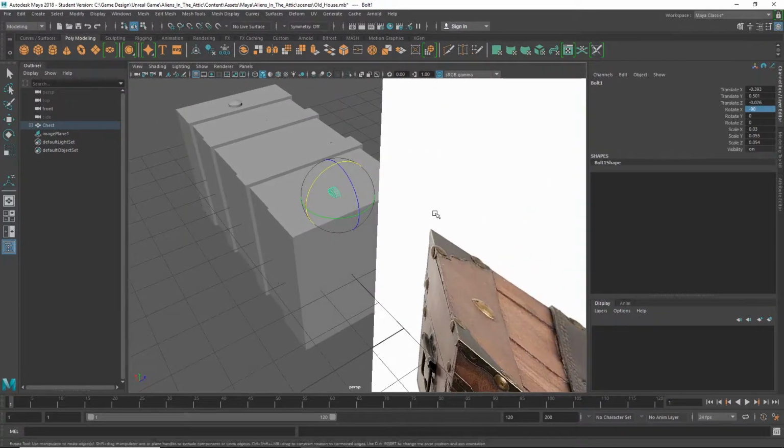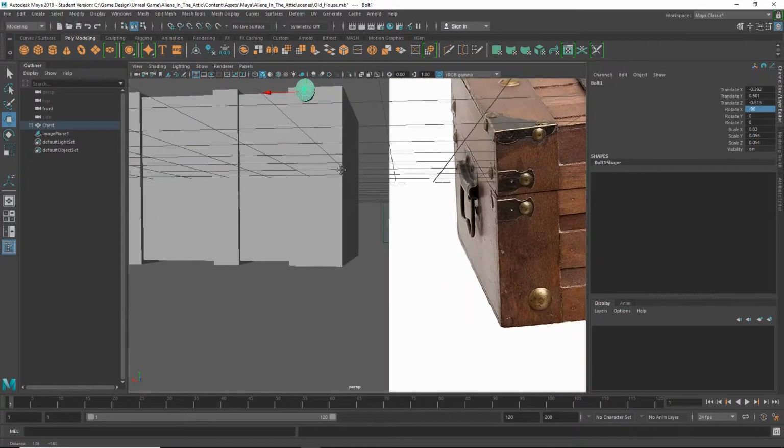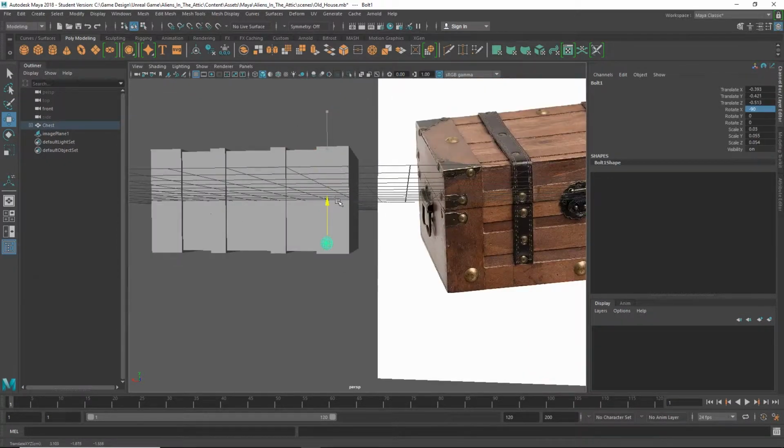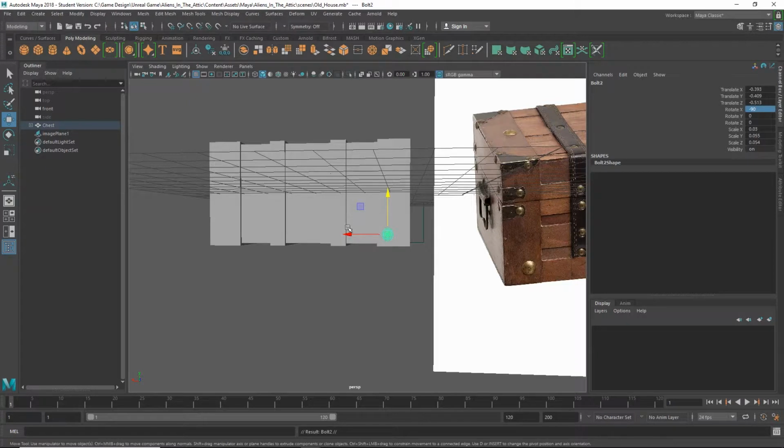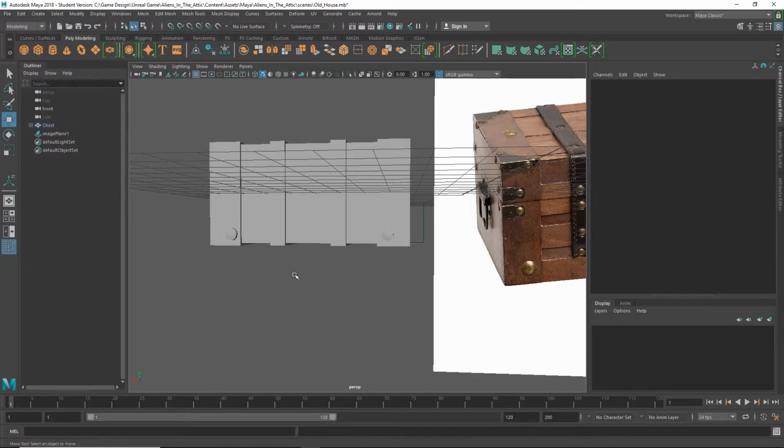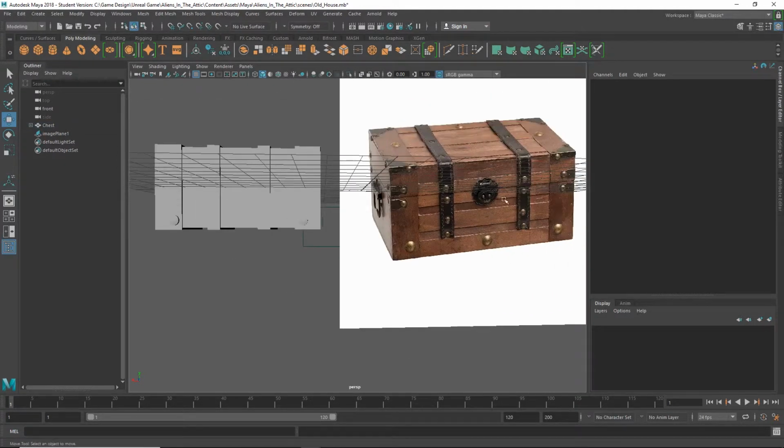Seems like a lot to learn, but when you master all these little things I'm showing you, you'll feel really confident as a modeler, and you'll just buzz through this really quickly. Once again, Control D to duplicate that over, and I've got these buttons or whatever they are. We also need to make some smaller versions for all of this. Looks like I've got one here in the center. I need Control D. We'll move it over.